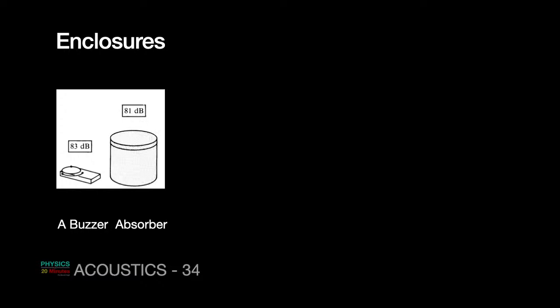It gives me a continuous sound of 83 dB if you put it on. Now if you put a simple acoustic tile container absorber kind of thing, you still get around 81 dB. So you can see that it is not very useful in the sense that a lot of sound is leaking out. Only a 3 dB drop has happened. If you keep it on an absorbing panel, remember here it is acting like a point source. Here half the sound will be absorbed and it will be down by 3 dB.